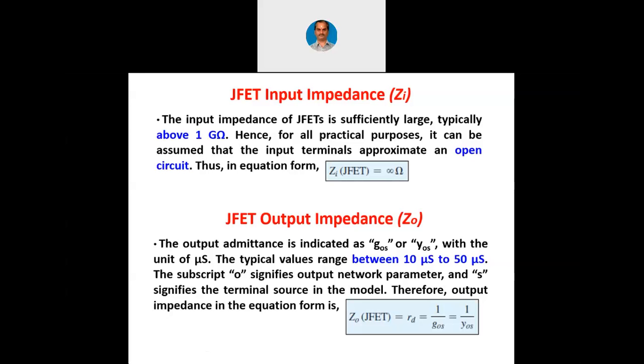But here we are not discussing the power amplifier. We will discuss the power amplifier in the last module of our course. Otherwise, we are discussing only the pre-amplifier stages. That means the amplifier stages which are at the input side, not at the output side. That is why here JFET is better than BJT in the sense that JFET's output impedance is larger than BJT. This is in contrast to whatever I told a few minutes before.